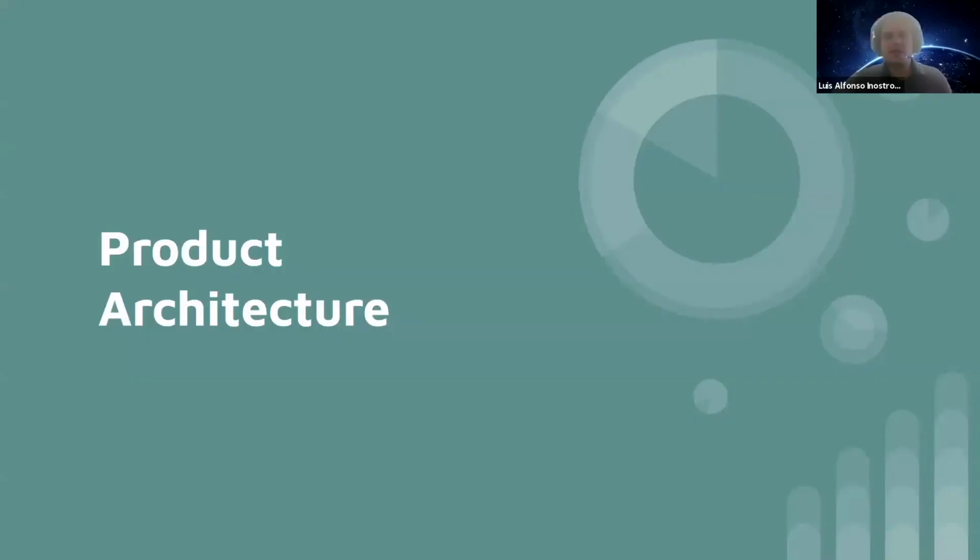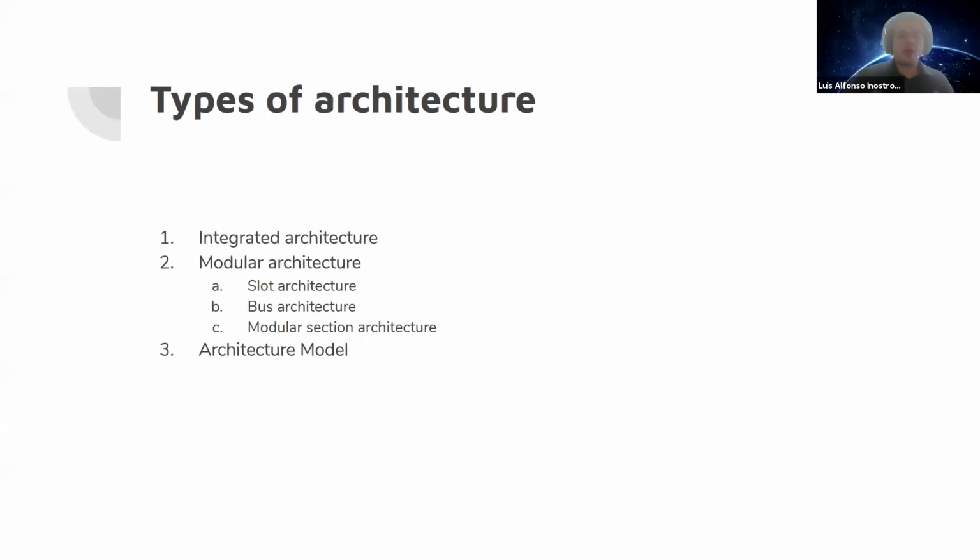Once you have all these options, you must make a product architecture of each one, which is a module of how everything is going to assemble together. You may choose different types of architecture like integrated or modular one, but in the end, you are going to make basic geometrical figures of the pieces that make up your product, and assembling them together in order to know if the geometrical relations between them are possible.